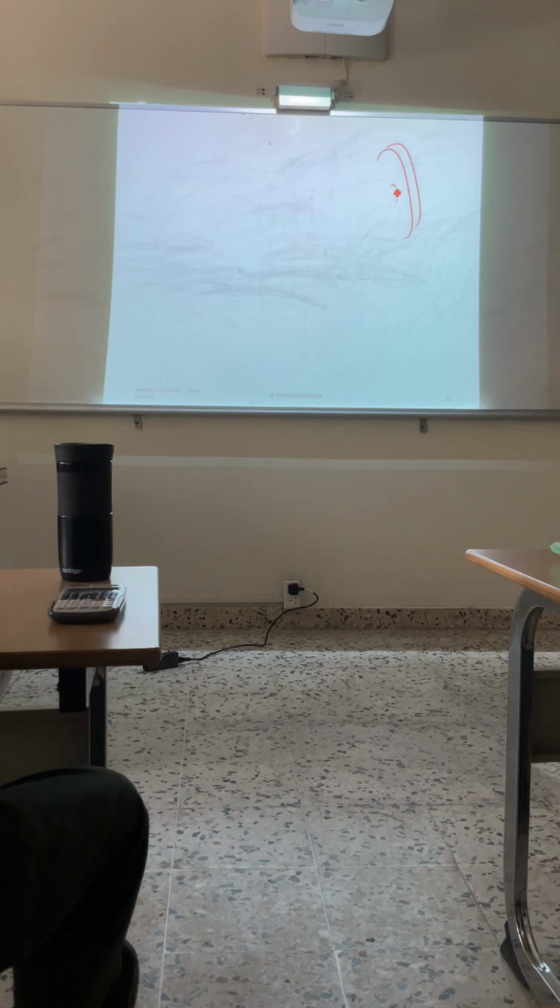Let's assume that this is a rotating disk and this is the source of the unbalance. It's called M, small m, or I can give it big M, it doesn't matter. As long as your disk or your shaft is rotating, this M will make a centrifugal force which is equal to M omega square R. Okay? And now, assuming that the scenario of adding the masses or removing the masses or adding the different masses in the same plane is impossible because of the nature of the machine.